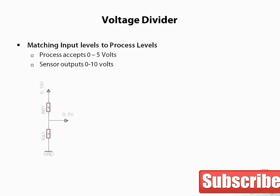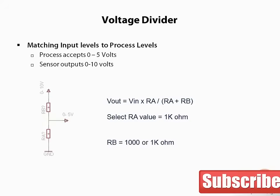Here is our circuit diagram again, except Vin equals 0 to 10 volts and Vout is equal to 0 to 5 volts. Looking at our equation again, Vout equals Vin times RA over Rtotal. Since our equation is ratiometric, mathematically it doesn't matter what the exact values of the resistors are, only the ratio of them. So for now, let's arbitrarily choose RA equal to 1 k ohm. Then solving for RB, it is also equal to 1 k ohm.